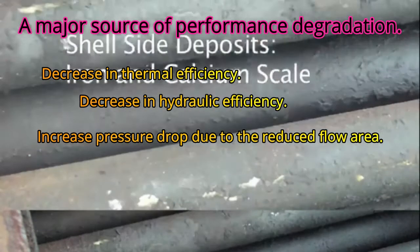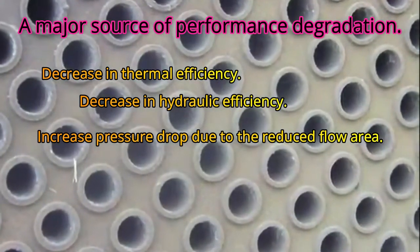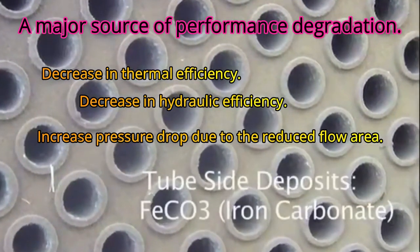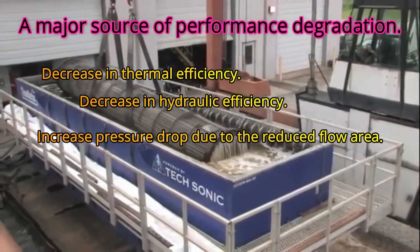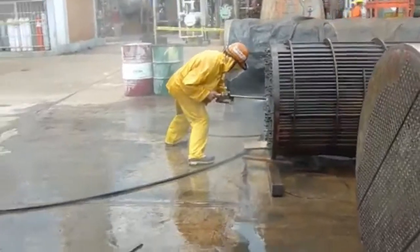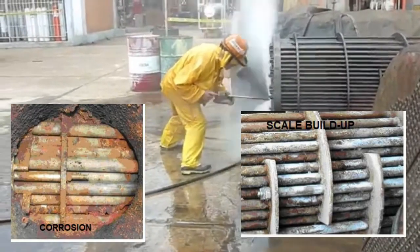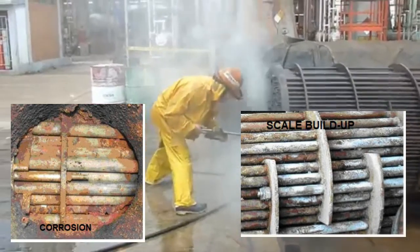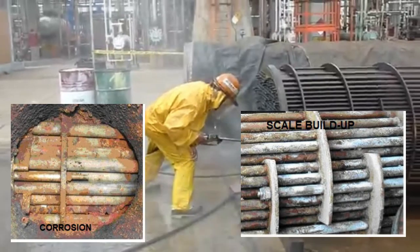In some cases, the degradation in hydraulic performance is greater than the degradation in thermal performance, which requires cleaning of the heat exchanger on a regular basis. Fouling of heat exchangers results in a number of ways. The two most common are corrosion and scale buildup. However, depending upon the nature of the fluid, other factors may contribute to fouling.